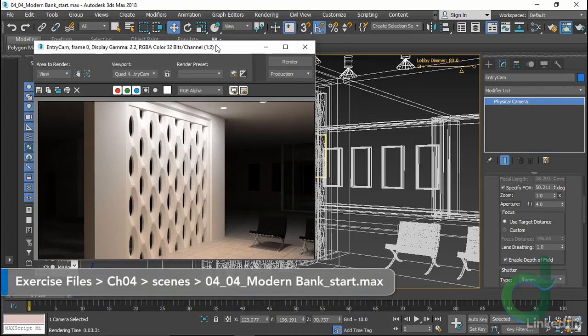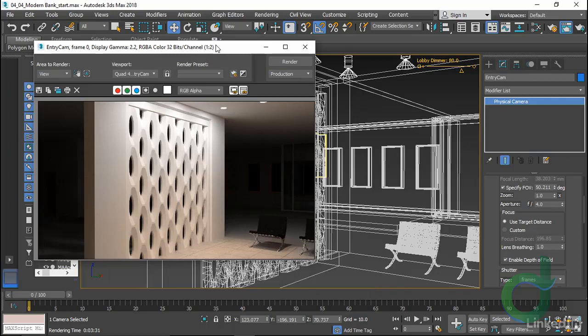Right now what I've done is simply put on that exposure so I'm not completely blowing out the scene. Actually, I've got a decent dim light going because there's no light fixtures in the rest of the building. I'm isolating the render down to this test case of this lobby. What I will do is typically play with the exposure settings to make sure that in a rendering, when I'm dealing in, let's say, sunlight or bright interiors, things will hold up nicely. That even with a nice bright exposure, I won't get too much blowing out.